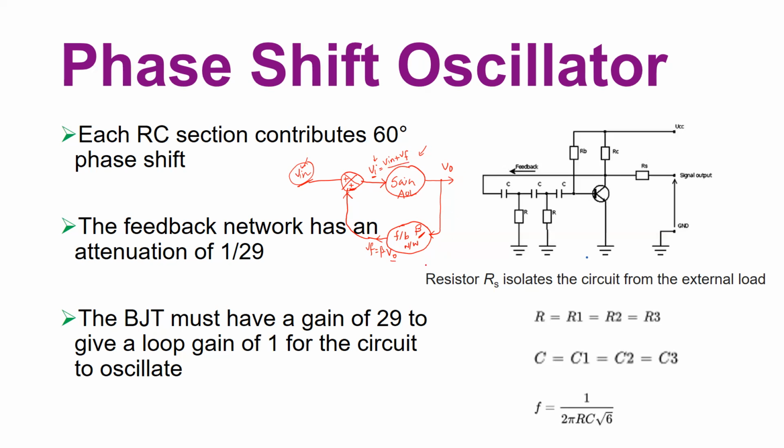So based on that, we saw that there is a transfer function, let us say Vo over Vi, and take the magnitude of it, and we say this is AOL divided by 1 plus-or-minus AOL times beta. So that's our final transfer function. From this equation, we understand that this is your open loop gain and this is your feedback factor. Beta is usually less than 1, which is why we call it an attenuation block, and here we call it a gain block.